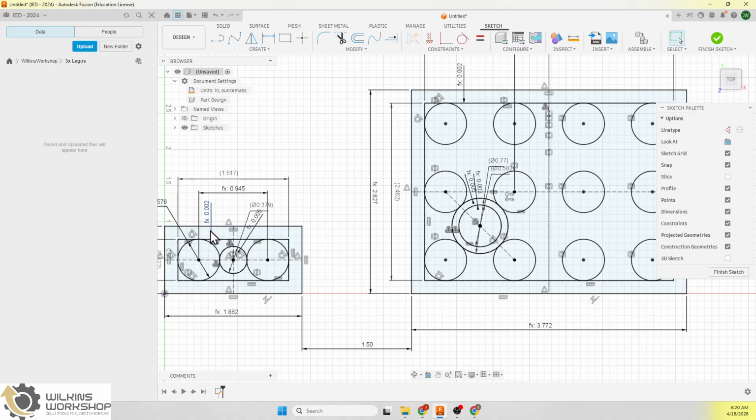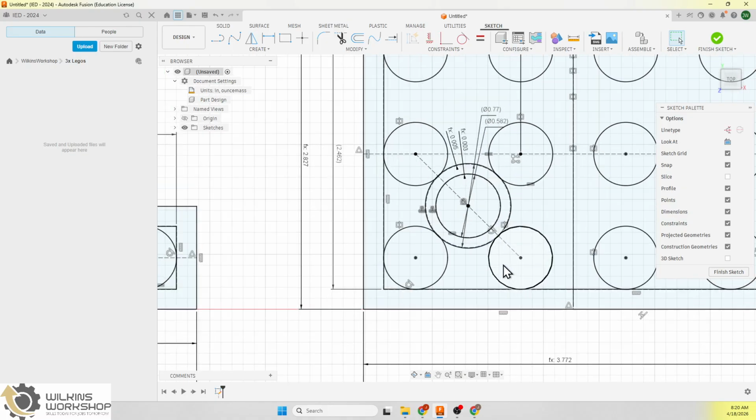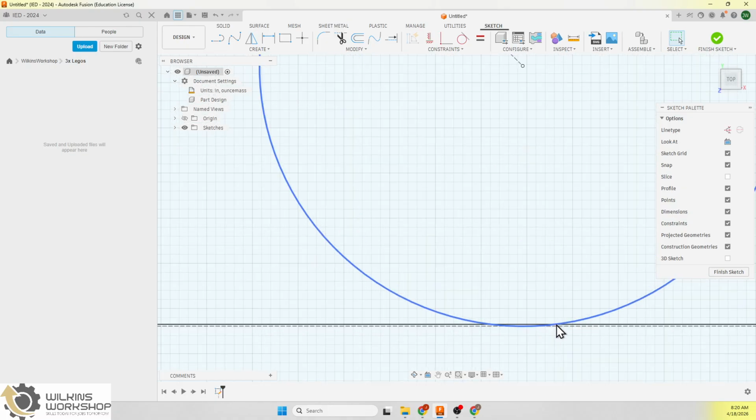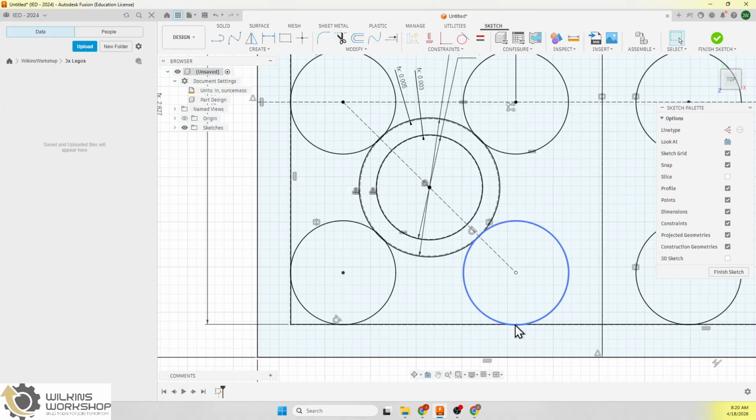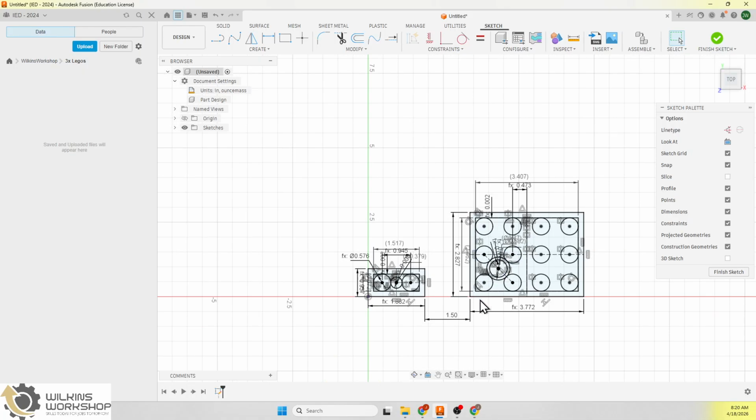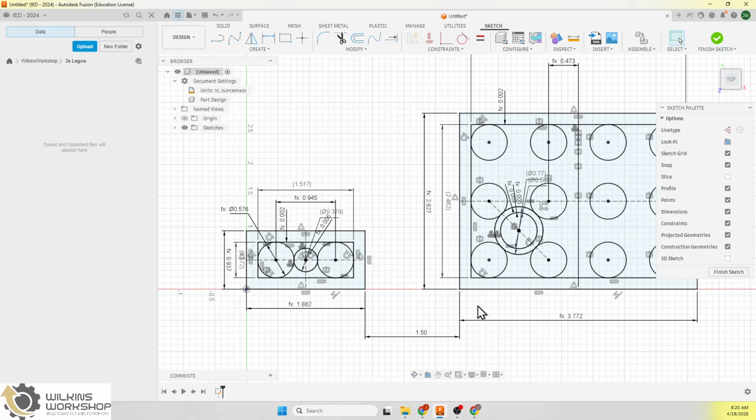So we're going to get one of these rolling, and if you make 2 1x2s, and then see how they press together. If they're sloppy, if they rotate, like if you put them together and you hold them up and they rotate, if you just put a single stud in there, then you have to make some adjustments to these numbers. But this is where we're going to start. We need some kind of starting point, and then we'll make adjustments to offsets as you go on your printing journey.